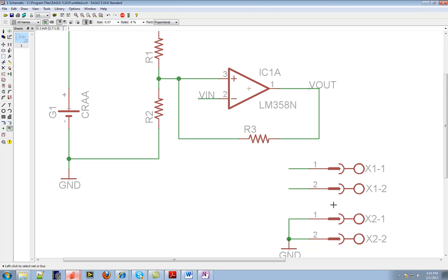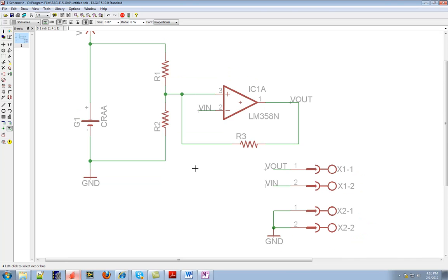And now I want to show the labels for each one of these. VOUT, VN. These are now connected to these virtually. If I want to see what's connected to what, I'm going to go to the eyeball tool up here, click on it, and when I tap the node here, you can see it's toggling the VN. It's telling me they're connected. When I click on the ground, this ground is connected to that. V plus.